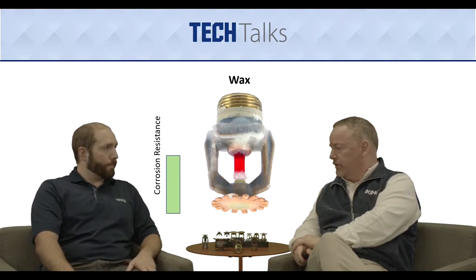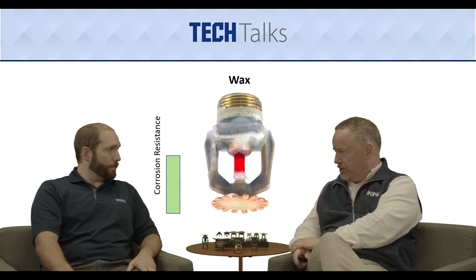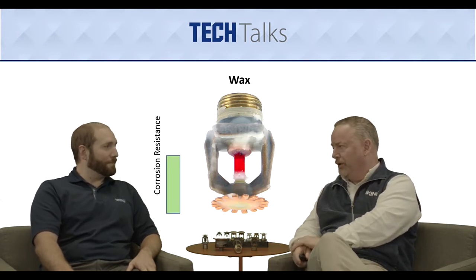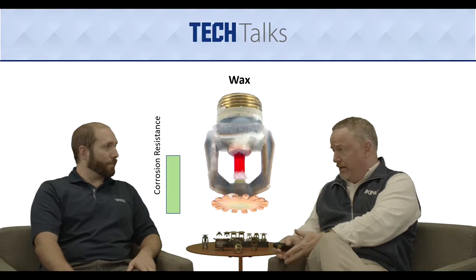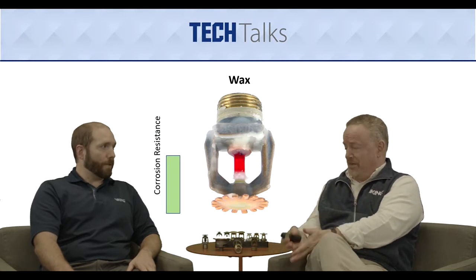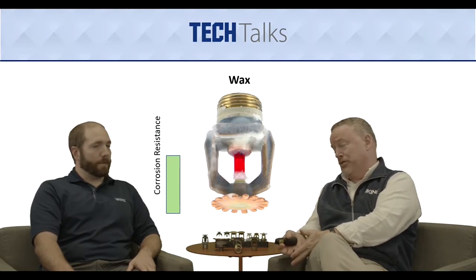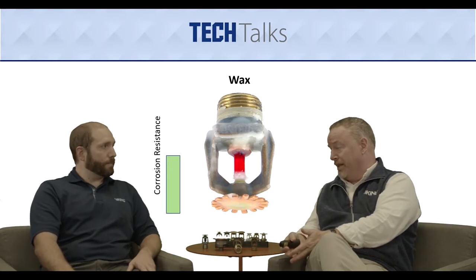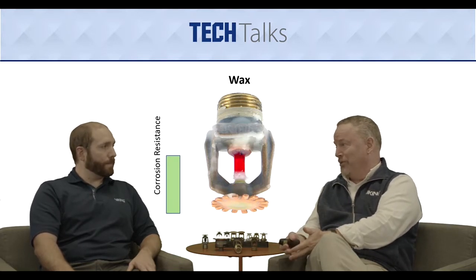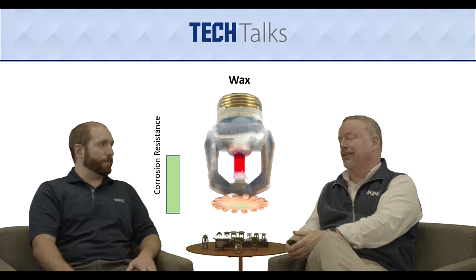Oh, okay. So your melting points change. That's a new one. Because if you've got higher temperatures, you basically have higher ambient temperatures, which is the reason you're putting in high temperature sprinklers anyway. And so you need to have a more durable wax. Yep, correct, absolutely.